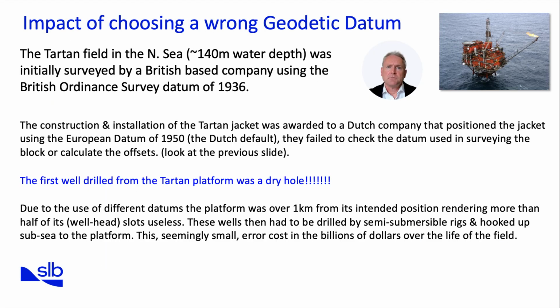What happens when we use the wrong datum? This slide illustrates the very real risks of choosing the wrong datum. A famous case occurred in the North Sea during the development of the Tartan field. The jacket was constructed by a Dutch company using the European Datum of 1950, their default, without verifying that it matched the British datum used to survey the field. As a result, the platform was positioned more than 1 kilometre away from where it was intended.